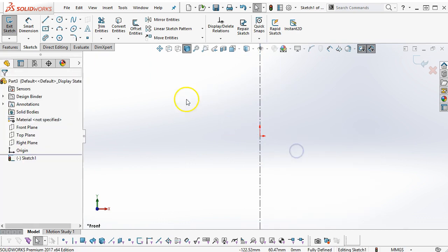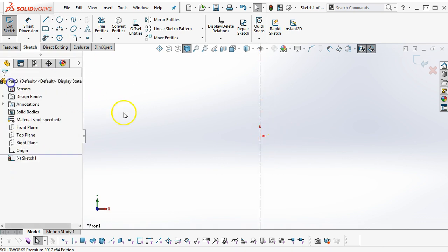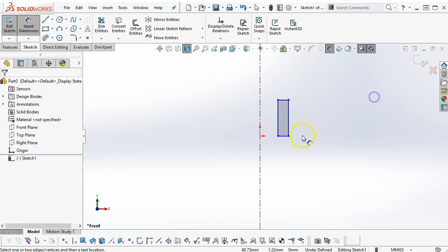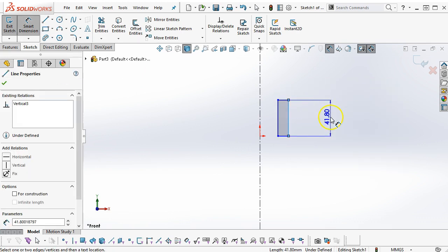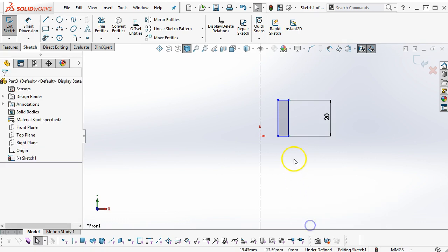All right, so center line, and my fingers were ahead of me again, so center line, vertical, infinite length, place it on the origin, we'll see that go to black. And then if I am creating, let me just put the height on this, 20 millimeters. If I leave a gap, then I'm creating a ring.